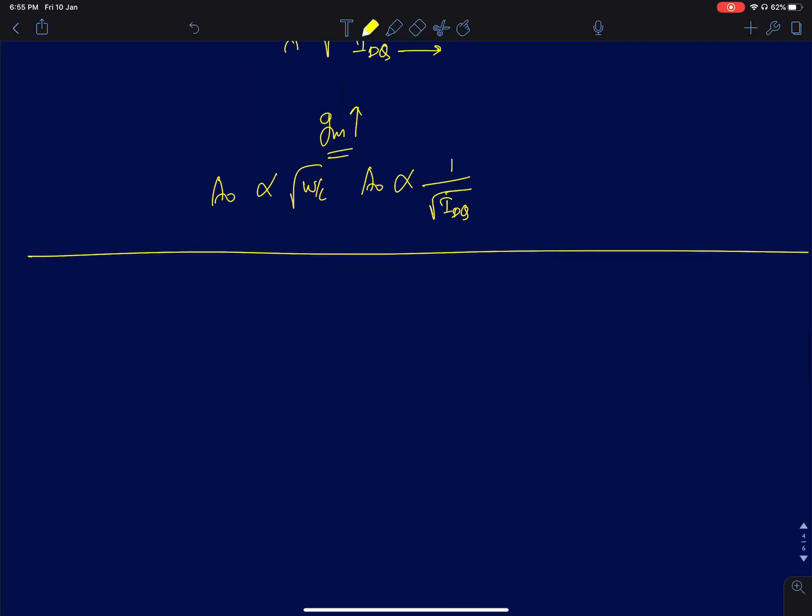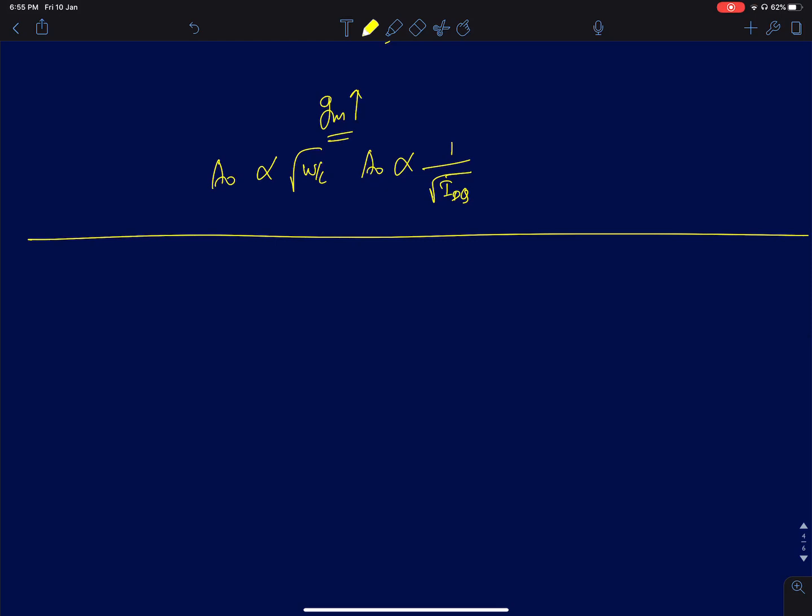So why do we care about intrinsic gain? When you use this amplifier, especially in integrated circuits, we will normally have stages like this wherein your load resistance will be a PMOS, which might be biased with some bias voltage. I'll just draw the AC model. So drain gate will be at AC ground and source will also be at AC ground, a PMOS device.